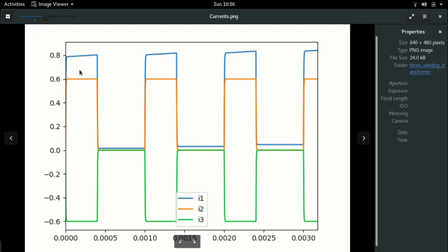So when the inverter is on and the voltage is high, you see the blue winding current is actually slightly increasing. Alright, there is a slight increase. The reason why there is a slight increase here is that this is when the magnetizing current is increasing. The magnetizing current in the transformer is increasing because remember there is an inductance. And if you run it for a long time, you will see that there is an increasing pattern, which means that the magnetizing current takes time to build up.